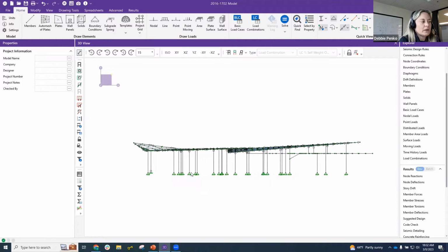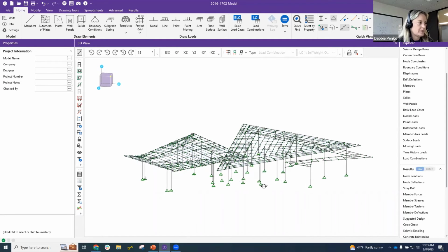I would tell you that a lot of times I use internal force summation for a section, just a little piece of the model, maybe at a moment frame where I'm looking for what's happening inside of that. And then I slice across there. You can also do it on wall panels. But this internal force summation tool helps you really slice across and get the analysis information out of your model based on what you're looking for. So that is a tool that you definitely need to pay attention to. I think it'll help you understand the model. So that's kind of all the things I wanted to show off in this model.